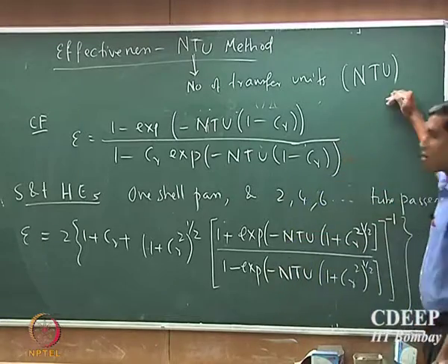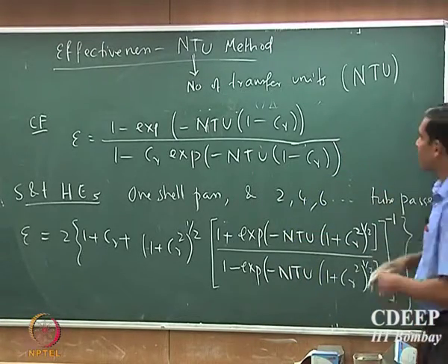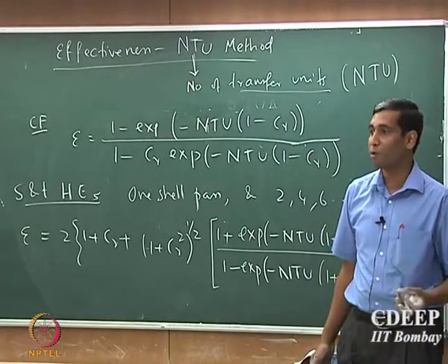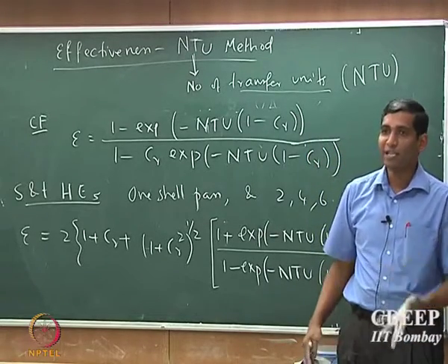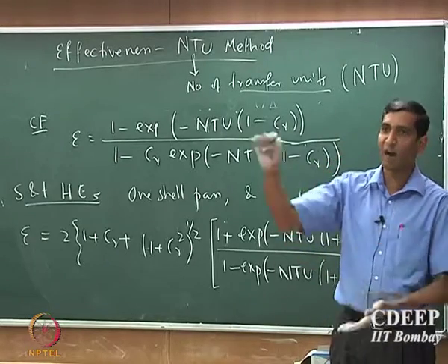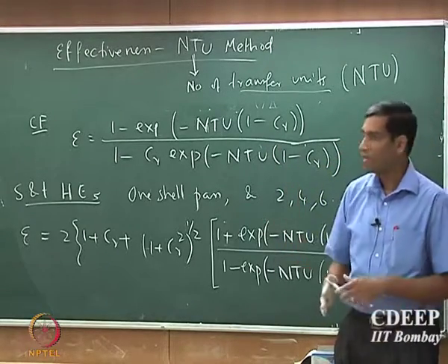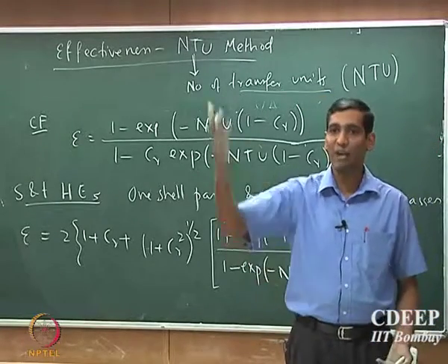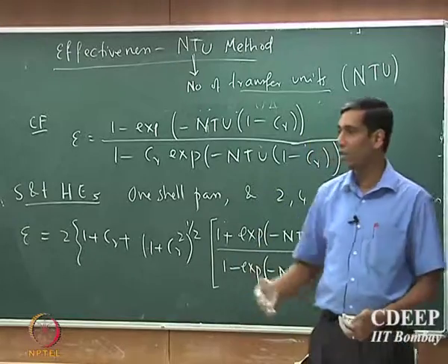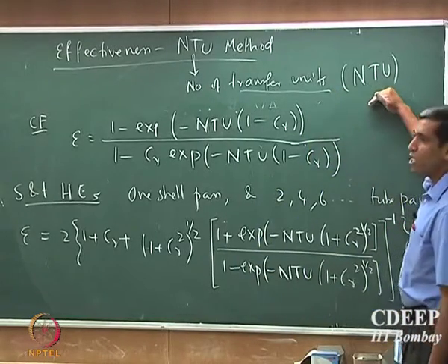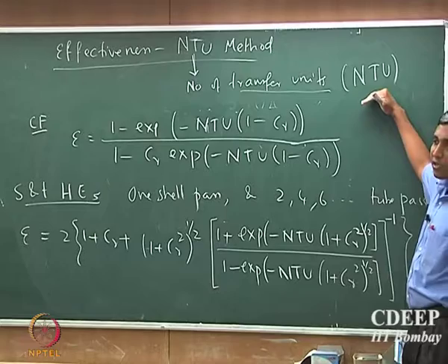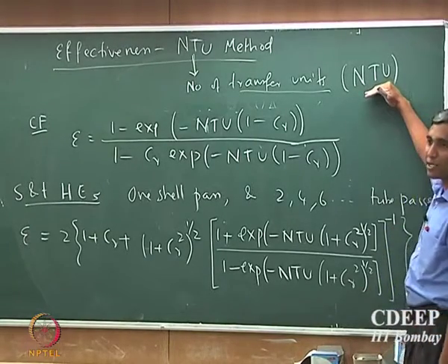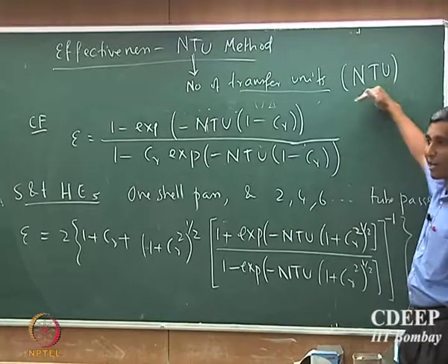You will see a lot more of the transfer unit concept in your mass transport operation course. In fact, when you design a tower, a distillation tower or any column, transfer units are used as standard units for designing the height, designing what the loading should be, etc. So NTU is an extremely important concept in chemical engineering, and I would strongly urge you to pay special attention to this and try to understand what this means.